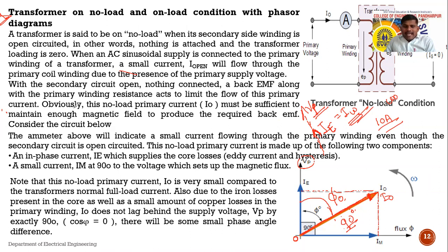Okay. Now, according to this we are deriving, or calculating, the value of I mu and IW. Once we get the value of I mu and IW, then we are able to calculate the value of no load current. Or once the no load current value is in your hand, then we are able to calculate the value of the magnetizing component and the working component.